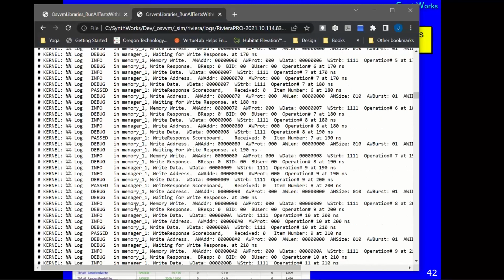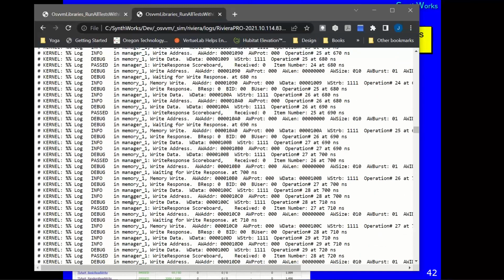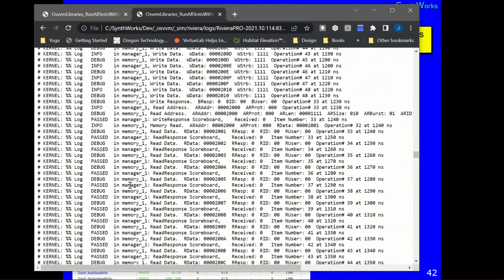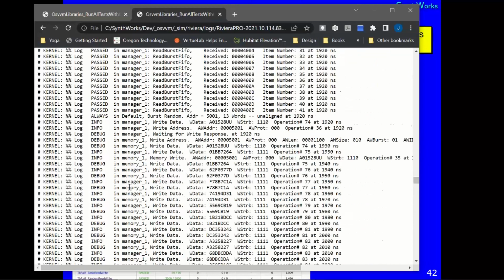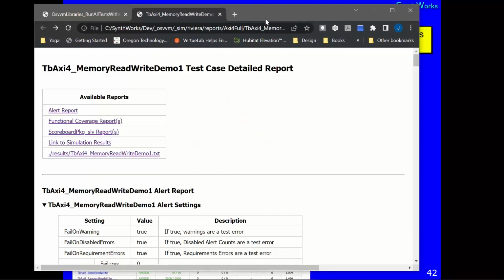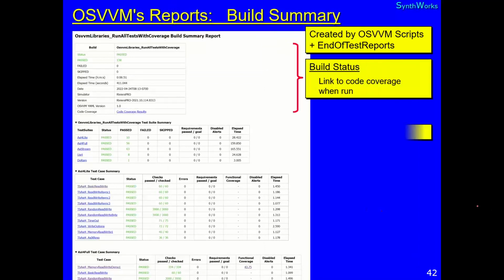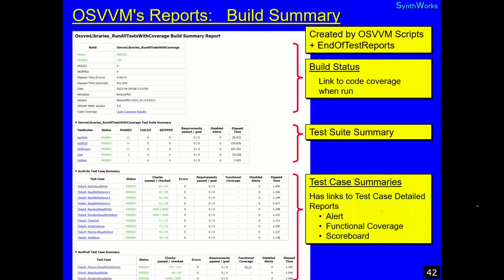So it automatically opened this one up and shows me what's going on in there, and all the results. You can see I had mirroring on here. Generally, I turn mirroring off when I'm running regression, so it's kind of interesting that it was on here. And I can quickly find if there was a bug in a test. This is part of helping me debug. If you go back to the surveys, like the Wilson verification survey, you'll see that debug takes like 48% of a verification engineer's time.